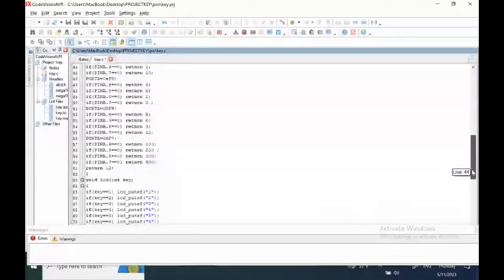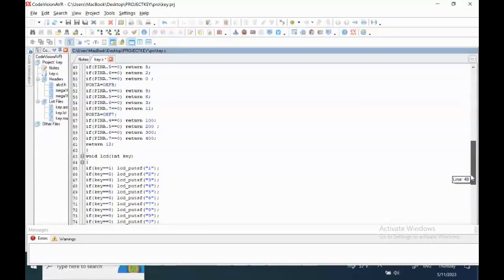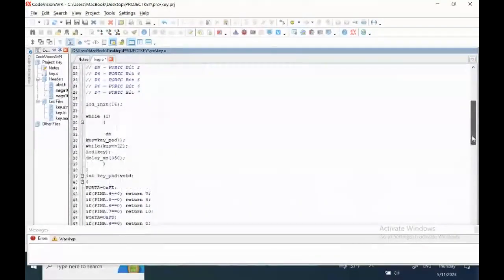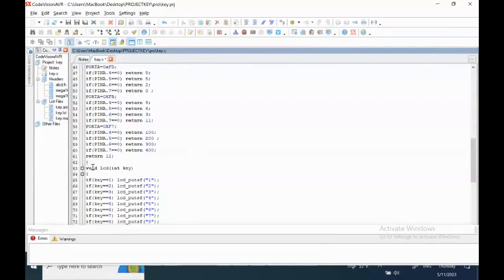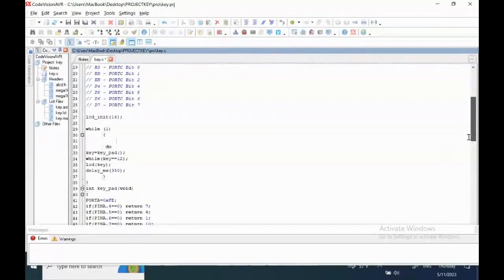So our program needs what? Do you know? We merged two user-defined functions. One of them is a return function; the return values are integer numbers. The other is a void function, and it is not returning anything, as you see, only executing something, printing something on the LCD. But as you see, inside while we are using the delay function.